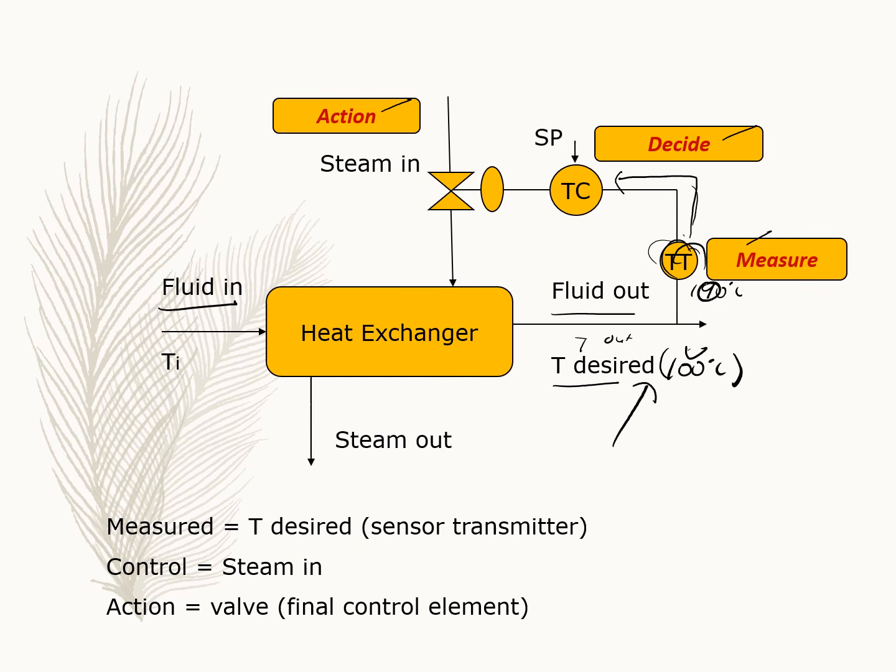It will compare whether it matches the set point here, which is 100 degrees Celsius, right? Because our desired value is 100 degrees Celsius, set point is the desired value of the process variable. The measured value is also 100 degrees Celsius, so there is no action that needs to be taken.